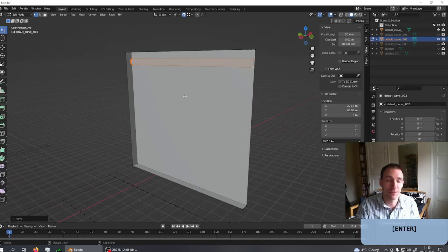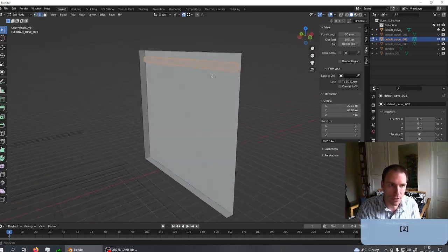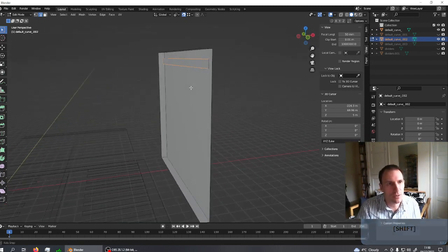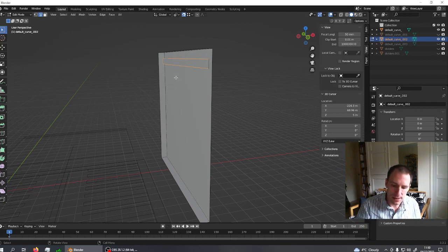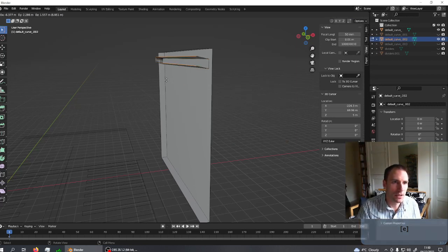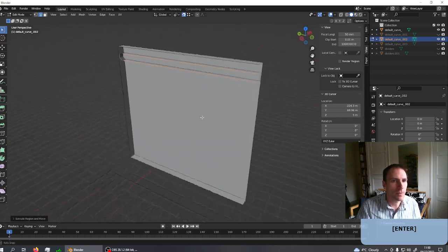Anybody who knows Blender knows that I am so doing this the hard way, but you could boolean this out. I'm kind of making a solid shape, because it might actually be useful. So I'm going to Shift and deselect that line, because Shift, Control and Alt are your main keys, and let's extrude. Let's go for on the x-axis, and let's make that 4, or actually -4. There we go. You can actually build a whole shape this way.